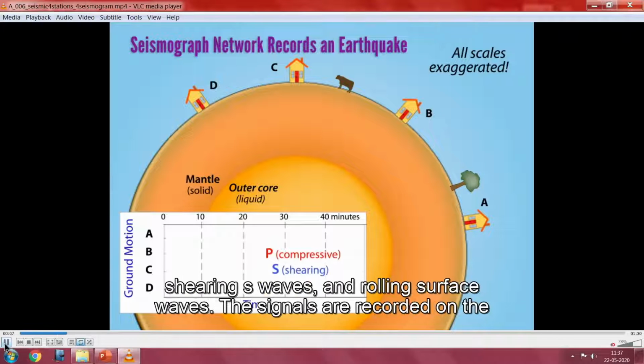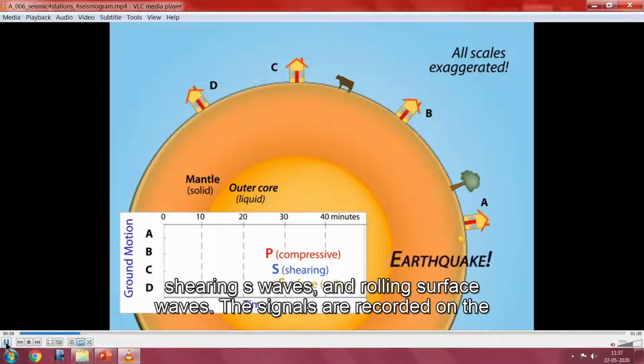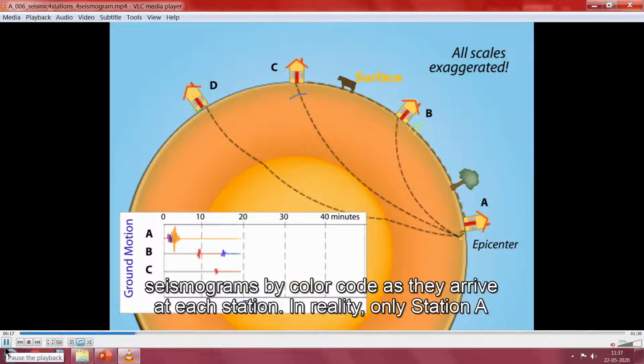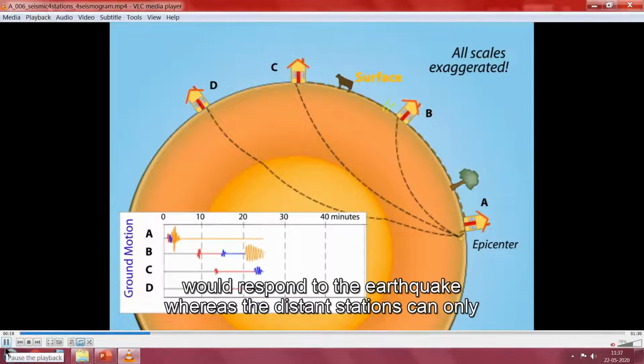So, I start the animation. Quake started, the S wave hit this, you can see here, then when the S wave goes here. See the S wave movement, see how it vibrates. Basically the building vibrates on S wave like this. Okay. So, when the surface wave comes, see the building carefully, the building moves like this.